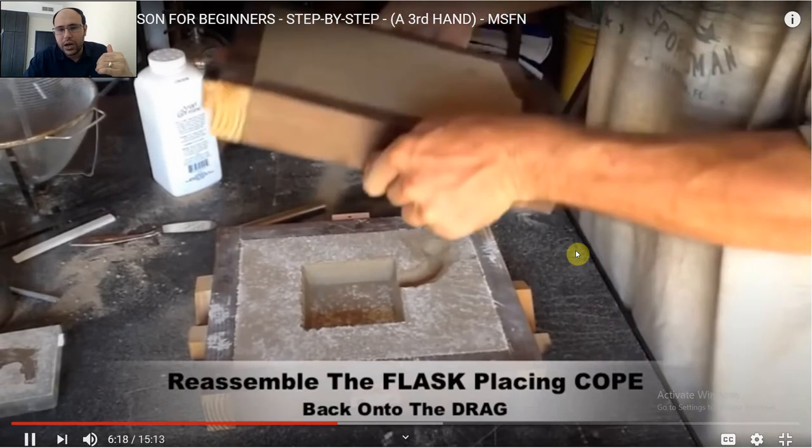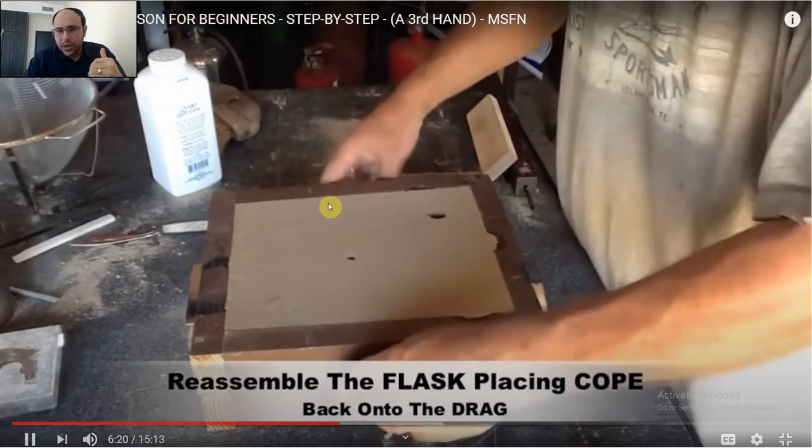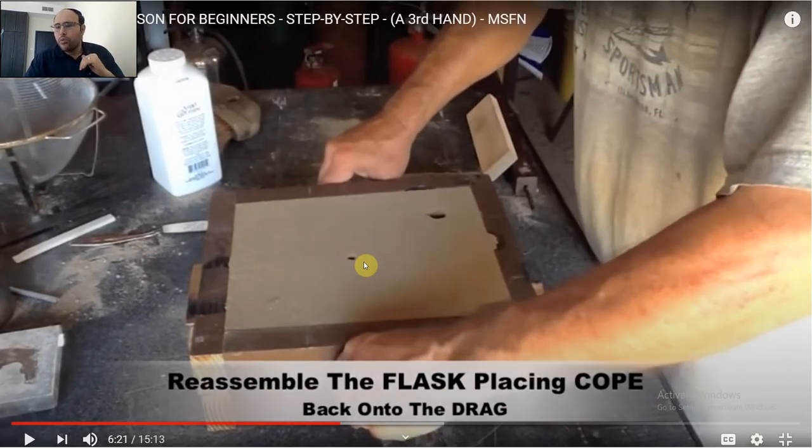Now it's time to put the half on it. As you can see, we already taken out the batten from the sand. So now simply if we pour the liquid from this opening, it's gonna go through the runner to fit into the mold, which is already empty inside.